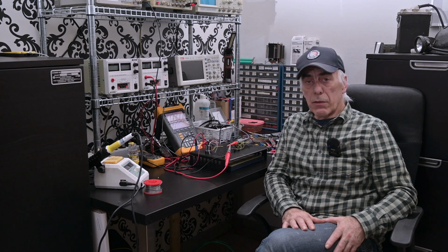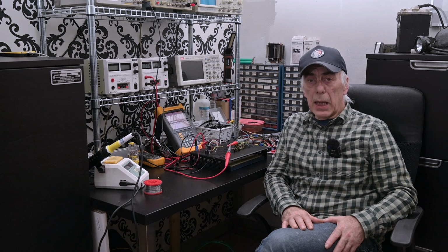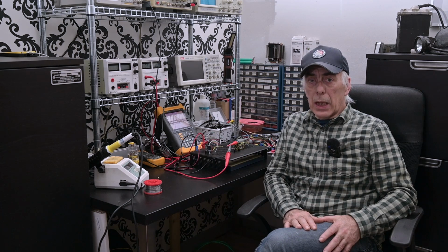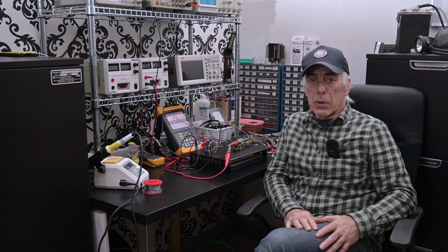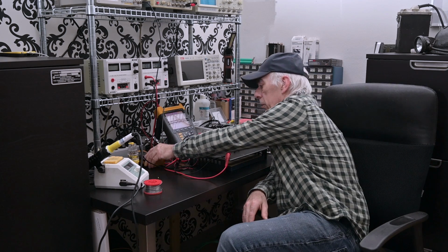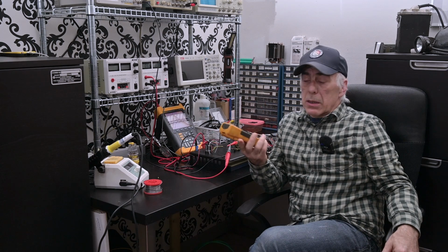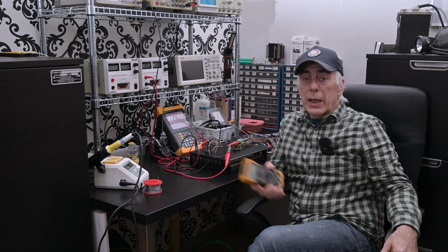What you have seen so far is the electrical behavior of the transceivers on a CAN bus. So now you know what kind of voltages to expect. Now the problem you will have on a CAN bus, if you're trying to read it with a voltmeter, it's not going to give you the right reading because these signals are switching way too fast.